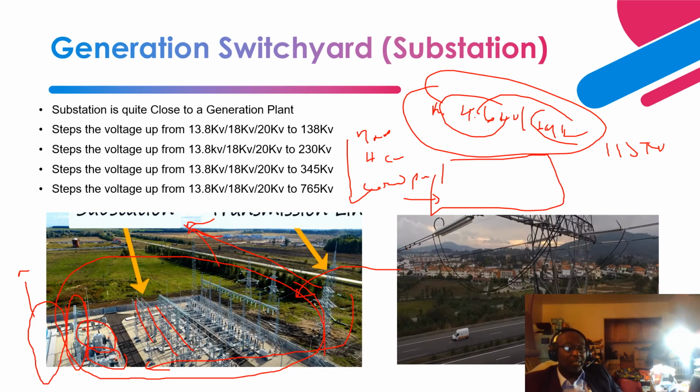So within this switch yard, we have different switches that are in place that basically are integrated to this 115 kV transmission line that is coming from a separate source, right? That comes in here to be stepped down to be fed to all these auxiliary motors and loads that basically help to keep the power plant cycle in place.